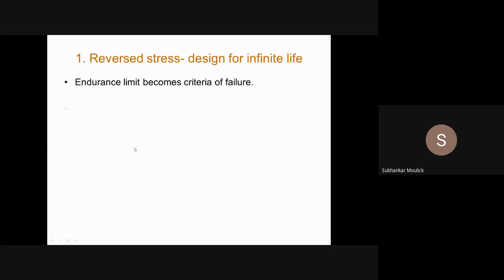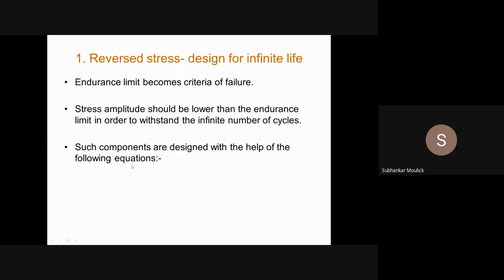And how to get this stress amplitude value? We can get it from the factor of safety equation. We know that factor of safety is failure stress by allowable stress. So allowable stress is failure stress by factor of safety.